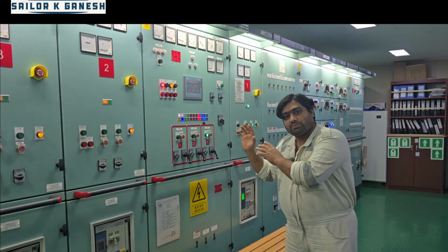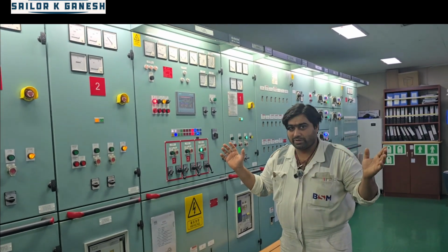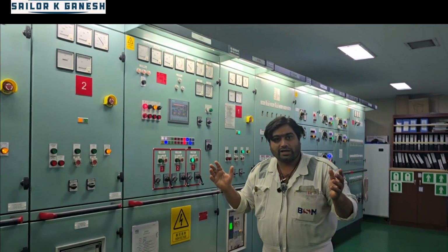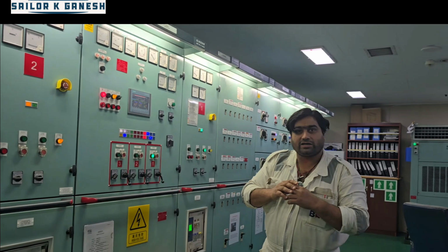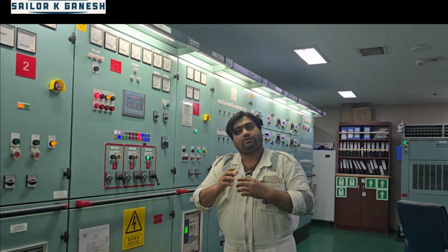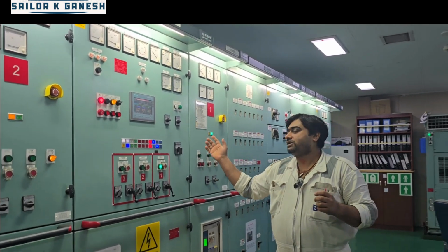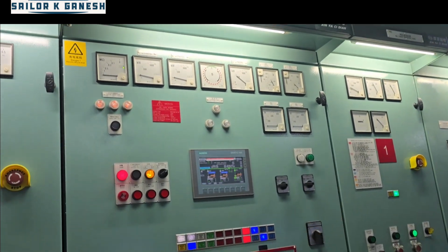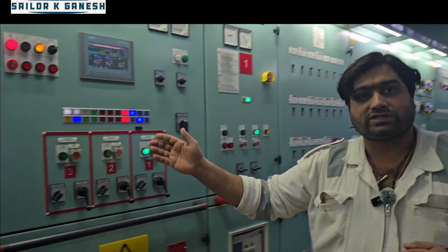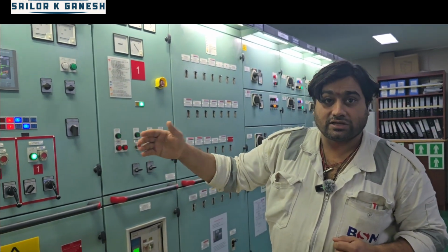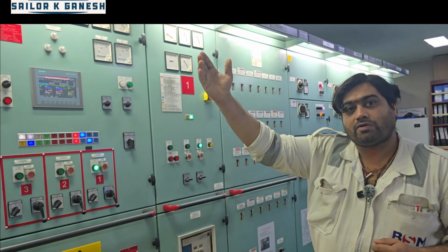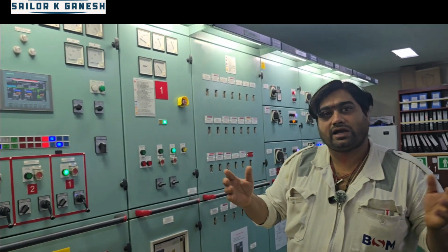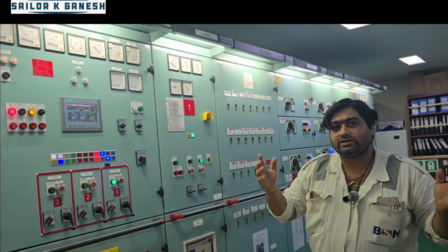The supply of power comes from the main generators. On the ship we have 3 main generators for the power supply, and we have 1 emergency generator in case of loss of power for the ship. If any of the generators loses power, the standby generator will start, and if that also fails, the other standby generator will start. If the third generator fails, the emergency generator will come on power, and then you can retain the power for running on emergency, and then again recover the power and run the ship in normal mode.